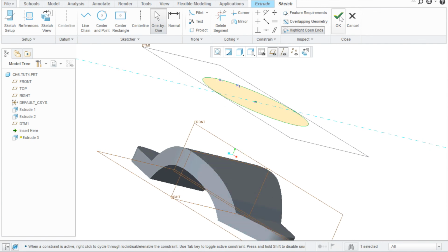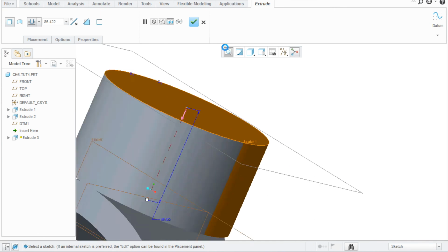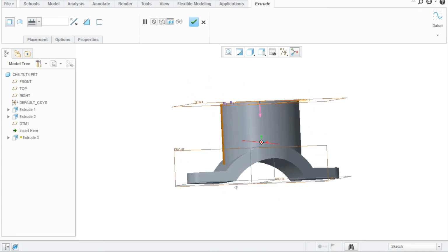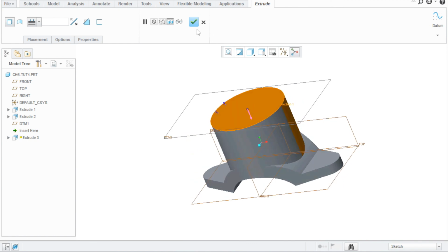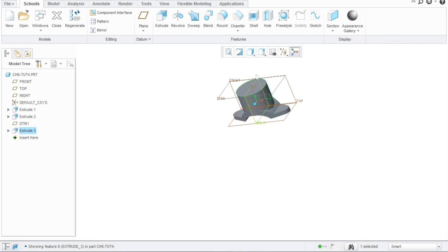So we're going to click check, and now that we know the direction, it has to go down. It's correct, and all we have to do is go to the next. Okay, just go to this icon. It says extrude up to the next surface, so it's going to flush it with the surface. Okay, everything is nicely done. Look at that. So we have it. Next, I'm going to show you how to create a counterbore hole.